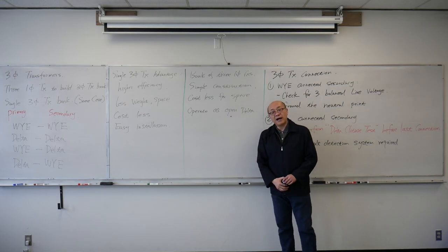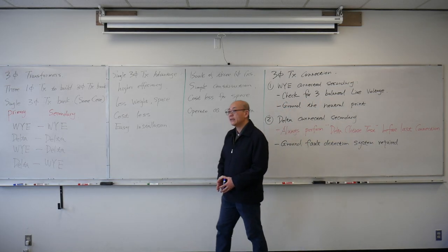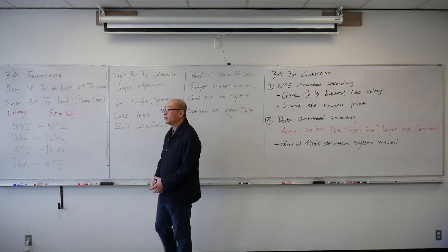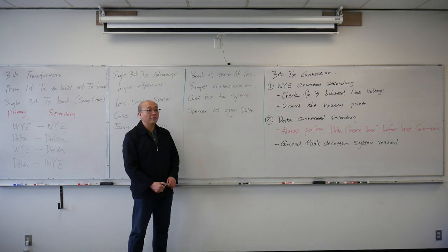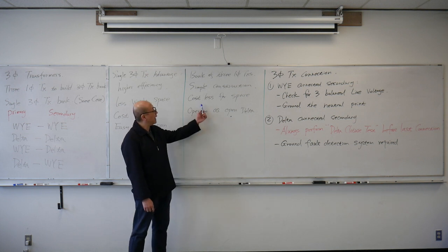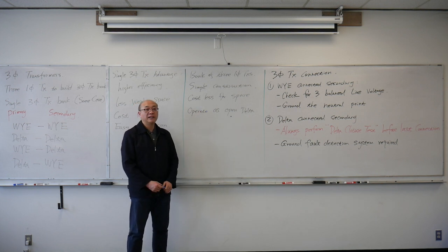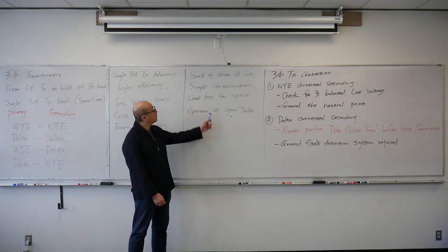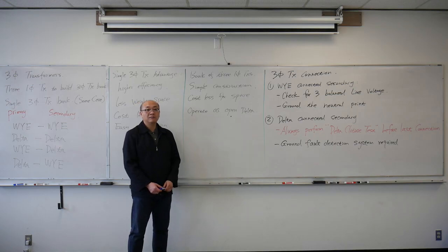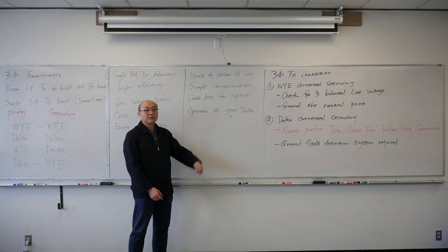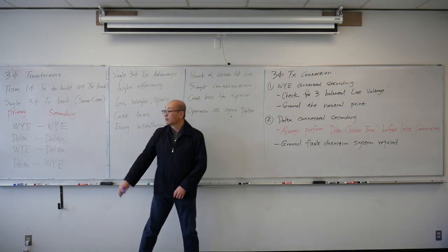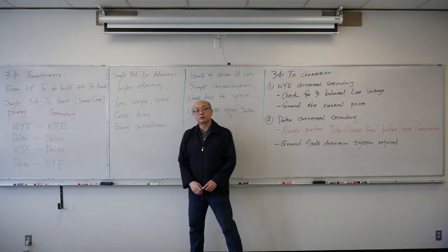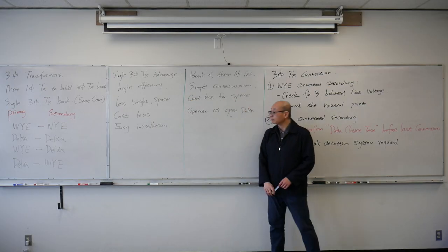Also, if I worry that something might go wrong, I want to buy a spare transformer. For three single-phase transformers, I only need to buy one spare. If any one of the transformers in that bank breaks down, I can just replace that one. So buying one spare is much cheaper than having to buy a whole three-phase transformer bank.